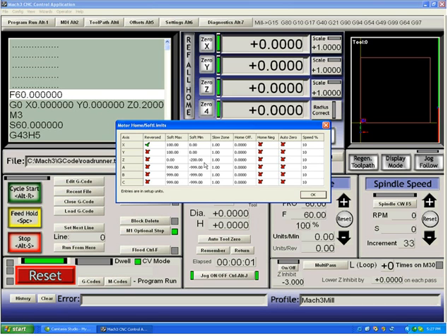Most people home their Z to the top. This is not true of plasma users, but for everyone else, it's very typical to home the Z at the top of its run, which becomes machine coordinate 0, because 0 in machine coordinates means next to the home switch. So make sure that when you're setting up your soft limits that you set a maximum of 0 for Z and minus 200 or whatever your throw is for your Z. Typically, your minimum in the Z is your full stroke movement in the minus direction.